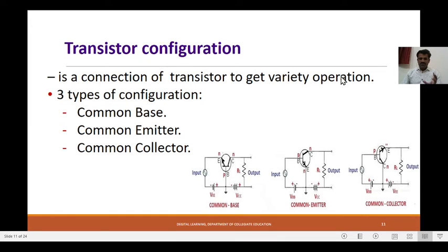And coming to the doping concentrations, we have studied them now. Now coming to how these regions will get connected. A transistor is a 3-terminal device. For any operation, we need input terminals and output terminals. For input, we need 2 terminals. For output, we need 2 terminals. Totally 4 are required, but we have only 3 regions, or connecting ports, in a transistor. So one should be common for both input and output.